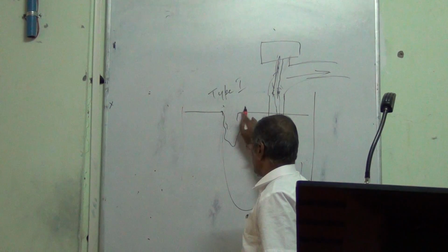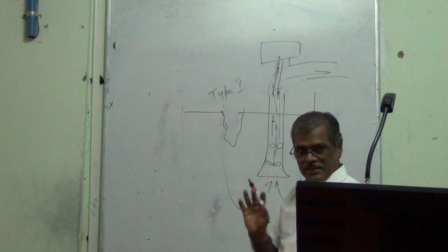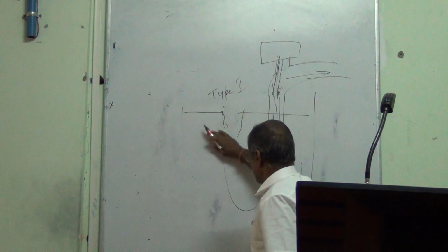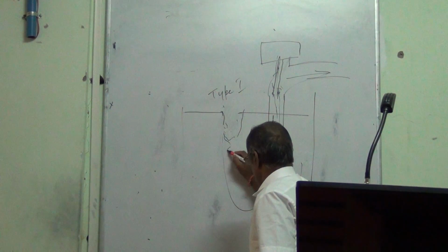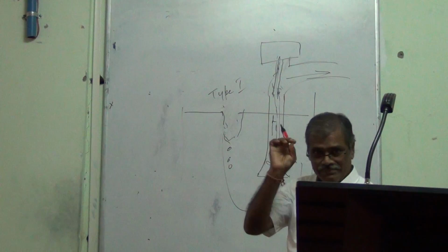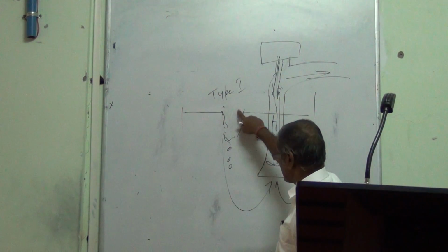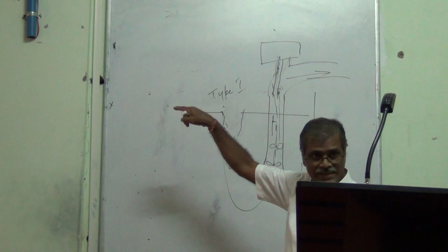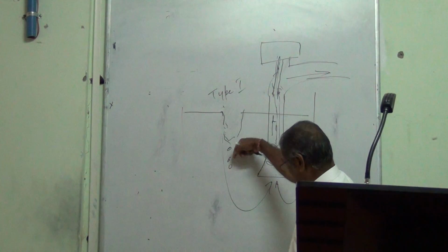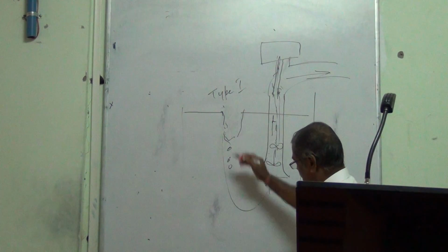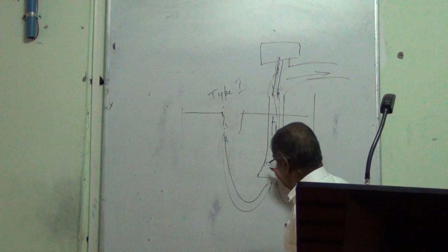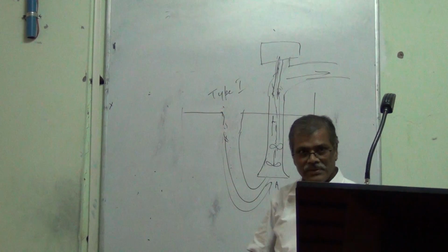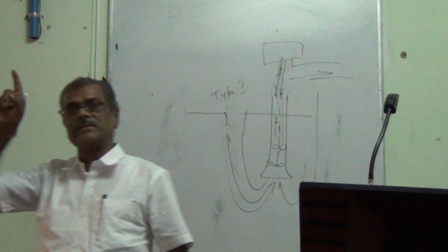Then bigger, and then still bigger with some air pockets. You see, this is air. There is no water here. This is a free surface, open channel. You understand that? And in the worst case, it will simply break the suction. All air entry, and the pump will fail.